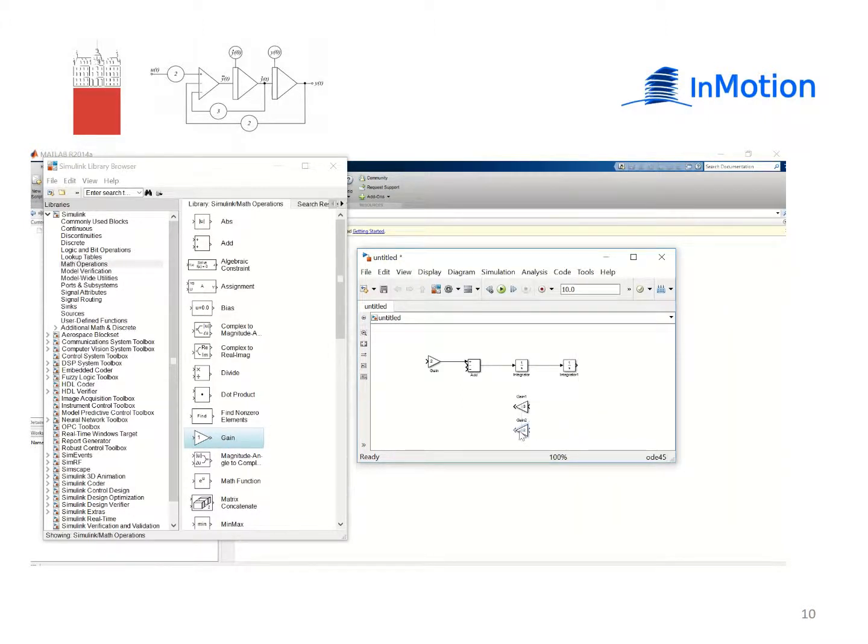And now I'm going to connect this gain 3 with the input minus of the summator and this gain 2 also with the input minus of the summator. Then we have to connect this gain with the output of the second integrator and this with the output of the first integrator. Now all the elements of our simulation model are correspondingly connected.